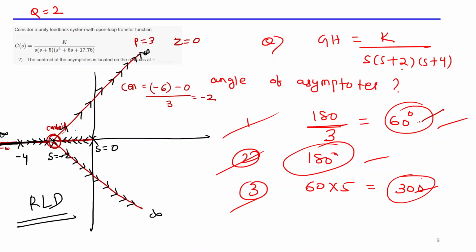Okay, so it is not exactly the same direction. Maybe the breakpoint is here, then these two poles will come and they will move parallel to the asymptotes. The root locus can be parallel to the asymptote. It need not exactly follow the asymptote, but remember that the root locus branches are always parallel to the asymptotes. It need not lie exactly on the asymptotes, but will follow them.